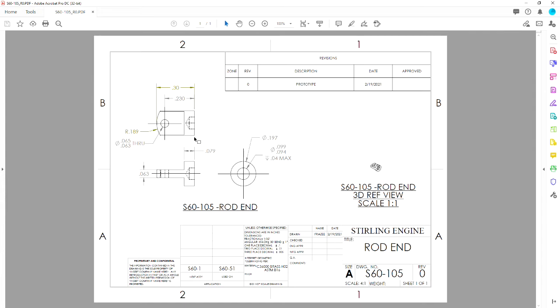But I believe to make this part with the least number of features, we'd start out with a Revolve feature that would represent the silhouette of the part in the top view. So it would just be these outside edges, and then we build all the other features as we go on the model. So this would be a multi-feature model unlike the last few you've done.